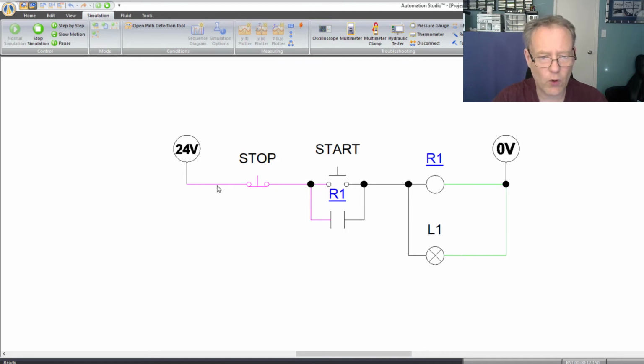There's potential voltage here. This green stuff indicates that there's negative voltage here, or 0. It's actually not negative voltage. It's the absence of voltage. It's 0. And this in between is simply not connected to any electrical conduction at all. So there's no electrical potential anywhere here. There's actually 0. We can say what the electrical potential is here. It's 0. We can say what the electrical potential is here. It's 24 volts.